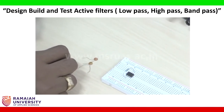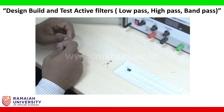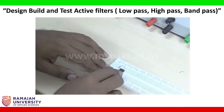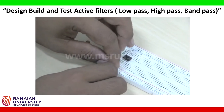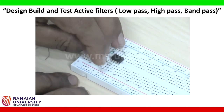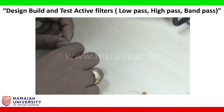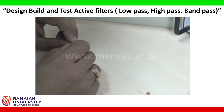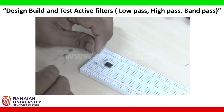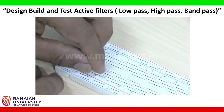Now I am going to connect the resistor 10 kilo ohm to pin number 2 to ground. So the resistor 10 kilo ohm will be connected to pin number 2, and pin number 2 to the ground I connected. So this is the ground connection. And I am taking a 1.6 kilo ohm resistor. I will connect the 1.6 kilo ohm resistor from pin number 3 to ground. So this is pin number 3 and I connected pin number 3 to ground with the 1.6 kilo ohm resistor.